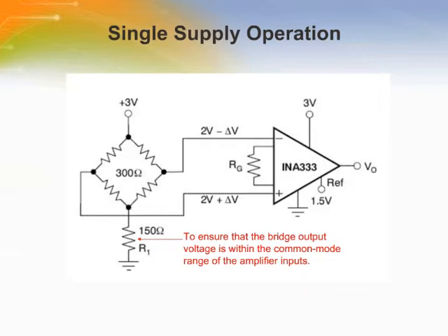When the load is referred to ground as shown with single supply operation, VIN+ and VIN- must both be 0.1 volts above ground for linear operation. For instance, the inverting input cannot be connected to ground to measure a voltage connected to the non-inverting input.